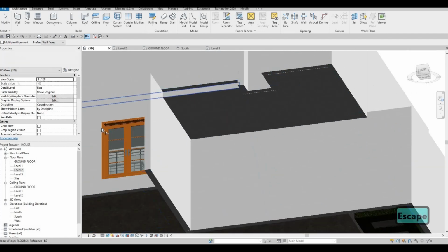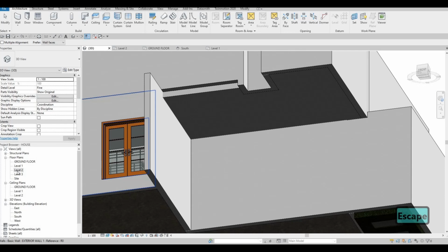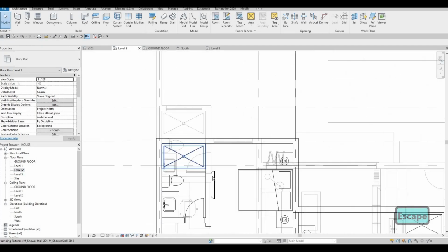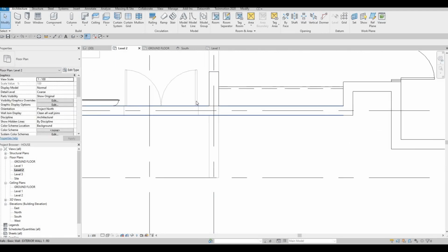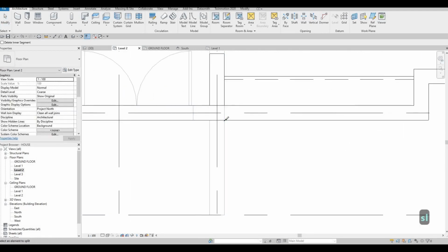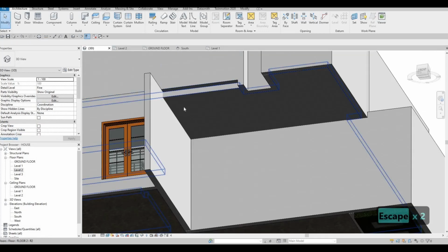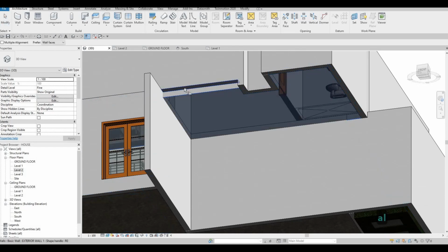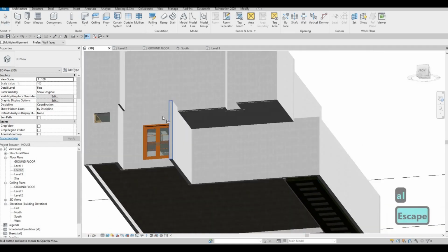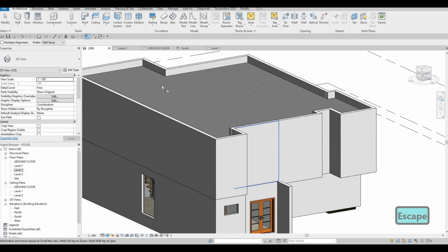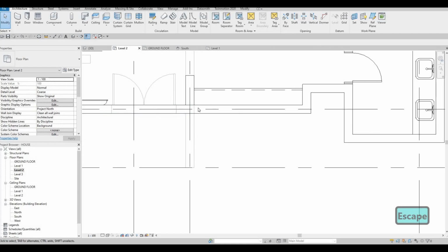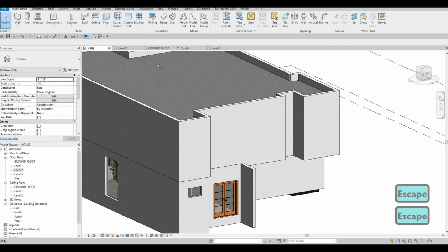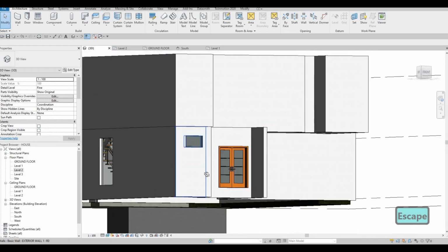But up to this point, we need to slice it. So we need to go to level 2 and look at where it is. So here, SL, we could click that one. So that's sliced already. We get AL, and then there we go. So this is now a 2 wall. There's 2 walls right here, and by using slice we were able to just unjoin them.